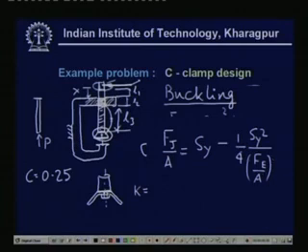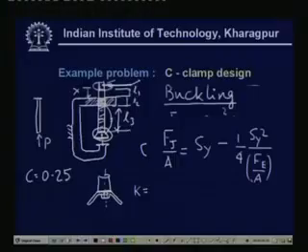We have to use this formula in order to check whether the given load is more or less than F j, once we have decided on the diameter, the core diameter. Definitely, if the load is more than F j, then we will have to increase the diameter by some amount, and then again we have to check with this formula. Now, this is about buckling.